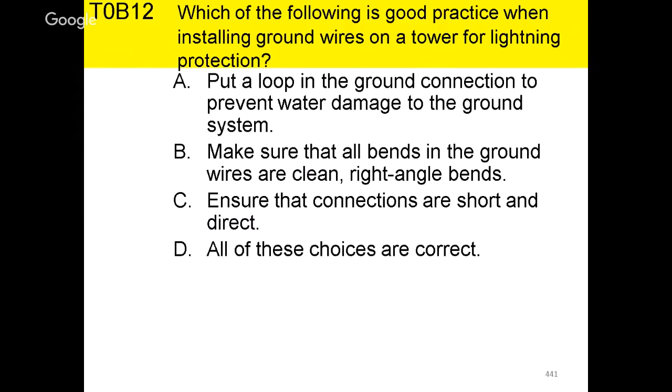Well, I already fixed it. I got 2 straps and a piece of number 6 wire and 2 clamps, and I put anti-oxidation compound on it after cleaning up the pipe and getting it bright and shiny, and I regrounded it. But how many other people are going to even know to do it, let alone take the time to get the stuff and make the repair? Exactly. Wow. That's interesting.